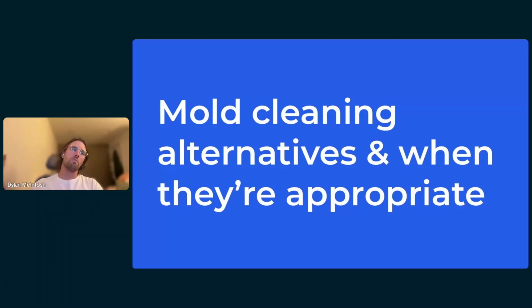Those spores that are on the surface may still be releasing slowly into the air for a significant amount of time. On a few square inches of mold growth, you could have millions of spores. And if those spores aren't removed from the environment, they can still cause health effects and other issues as well, even if they're not currently reproducing. Even non-viable or dead mold can cause allergic and other reactions in individuals. So that's why all professional reference materials on mold remediation consider remediation to be the removal of mold from the environment, not just the killing or deactivating of mold.